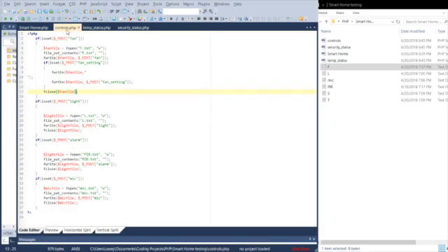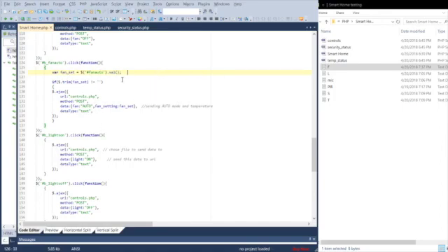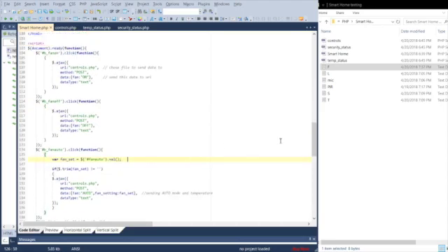So inside our control setting, we're going to say, since all of the buttons actually call the controls.php file, first it has to determine which button was pressed. So it could be the fan, it could be the light, it could be the alarm, or the microphone. Since it was the fan, it's going to run this. It's going to open f.txt. It's going to clear it. It's going to write the fan setting to it, the new fan status, I guess, which is either on, off, or auto. And if it's auto, then we'll also have our fan setting, which we wrote back in the last file. Our fan setting we will put in the file as well. Then we will close the file, right? And that's exactly how we put the data in a file. And after we press the button, the data will be read by our Python, and physical actions will be performed, like turning on the fan.